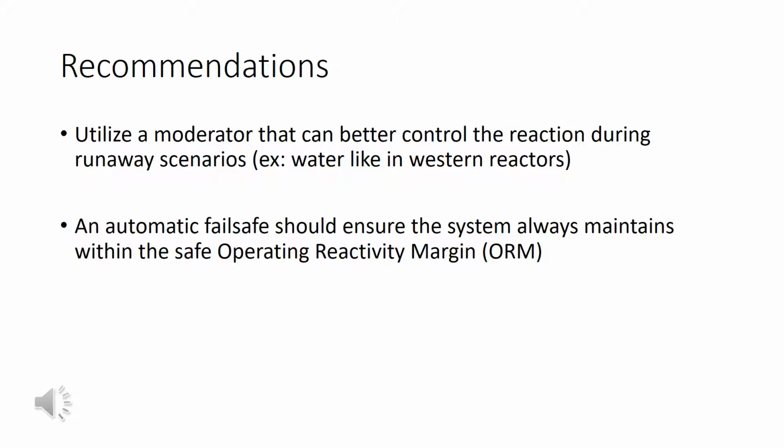Additionally, there would be a third AND branch leading to the top gate, where the water acting as a moderator would have to have an additional failure such as a leak or rupture to result in the core breach. The additional AND loop would significantly decrease the probability of the event because AND gates multiply in the probability matrix.